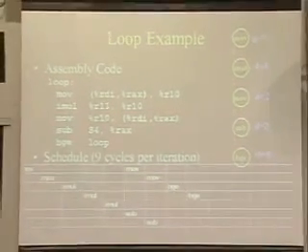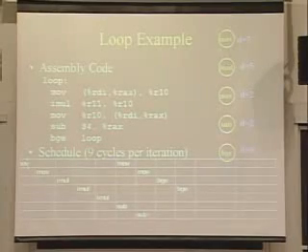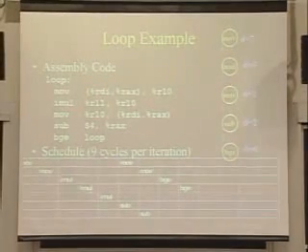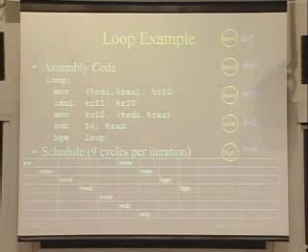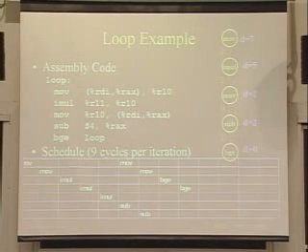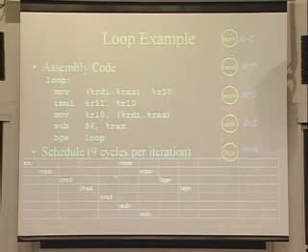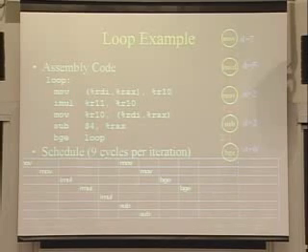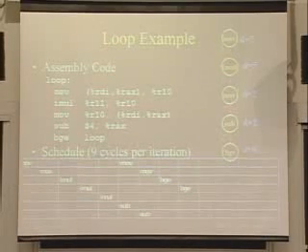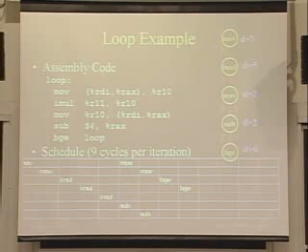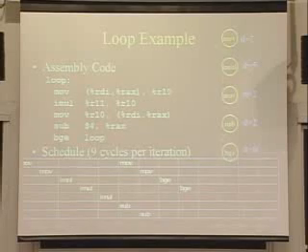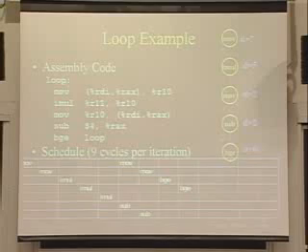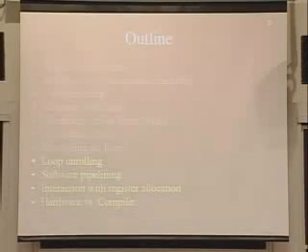So if you run this, first you do the move, followed by the multiplication, which takes 3 cycles, and then the subtraction. When you start the subtraction, you can do the next move, followed by the branch. So this is basically the best you could assume you can get. I'm not dealing with any resources or anything like that. I'm just looking at the pipeline stages you have to do. Okay, is this clear, how this goes? So okay, this is good. It doesn't give you that much. This is basically what the normal schedule would do.